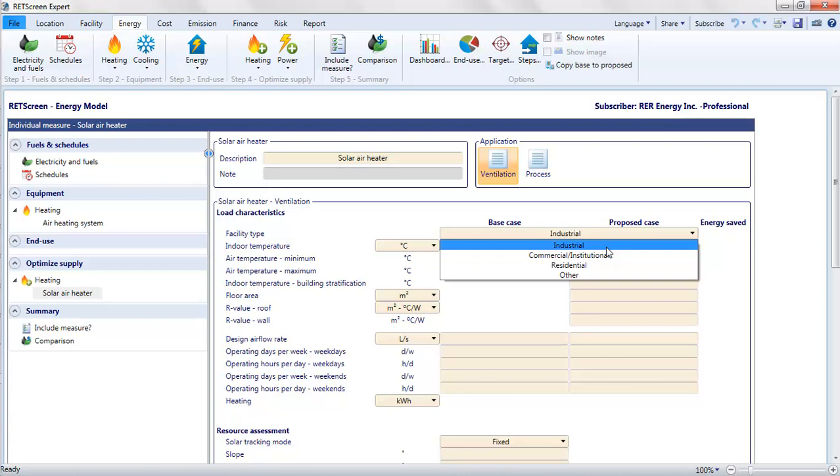In such a system, the flow rate through the collector is reduced when the air exiting the collector is below the minimum desired temperature. This does two things. First, with a lower flow rate, air resides in the collector longer and is therefore heated to a higher temperature. Second, the difference between the design air flow rate and the reduced collector flow rate is made up by inside air drawn from near the ceiling and mixed with the solar air. This reduction in the collector flow rate is such that the temperature of the mixed air attains the desired minimum.